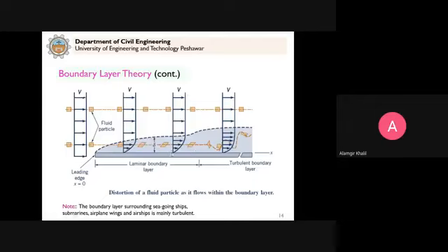So now you saw what a boundary layer is. This is an important concept, and you already saw in the previous slide that this boundary layer develops. Now we come to see the big picture. The same concepts that we studied in pipe flow appear here. The boundary layer can be a laminar boundary layer, or it can be a turbulent boundary layer, or it can be a transition regime.